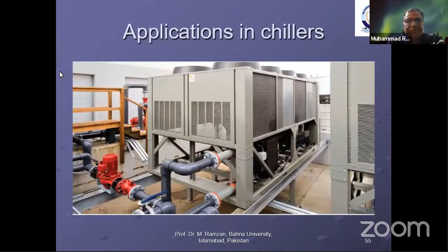Application in chillers. Many reported a 40% increase in the thermal conductivity for 0.4% volume fraction of nanofluids. This gives an opportunity for improving performance of the chillers in air conditioning systems. Surprisingly, the cooling capacity of the nanofluids could increase by 4.2% at the standard rating conditions. A 6.7% increase in capacity was achieved at a flow rate of 60 liters per minute.